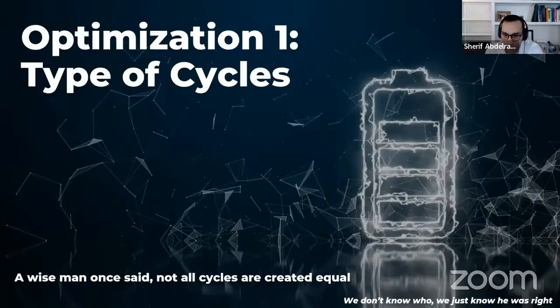If you have two exactly similar projects, one of them is running really deep charges going from 90% down to 5% or to 10%, and the other is just hovering around 50% or so state of charge, while executing the same number of equivalent cycles per day. So both are 1 cycle a day applications. How different degradation do you get? And based on that, how much different does your overbuild capacity or your beginning of life capacity need to be?